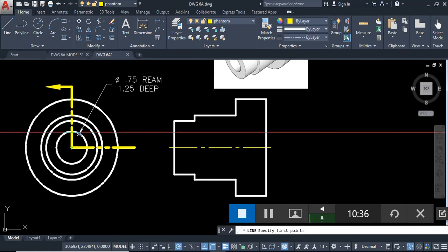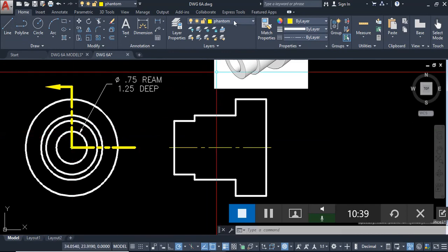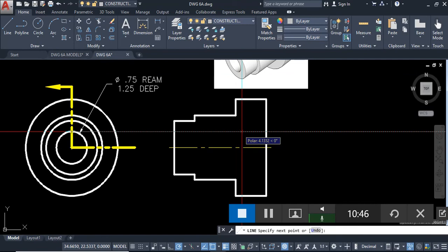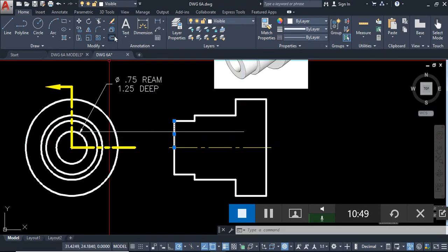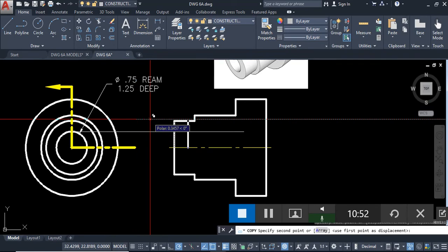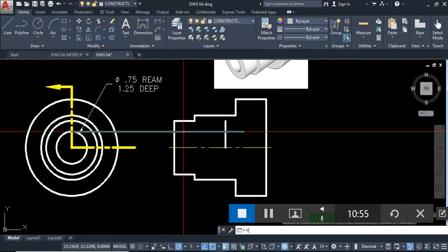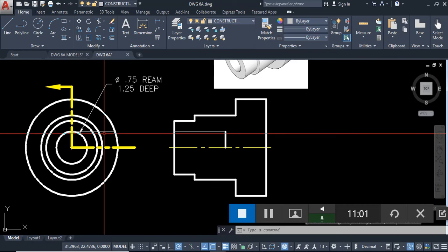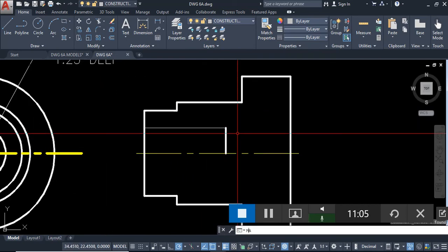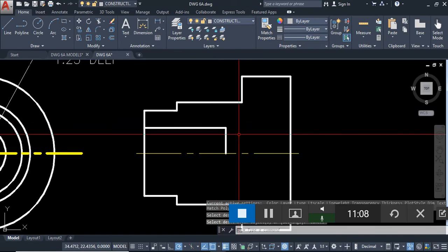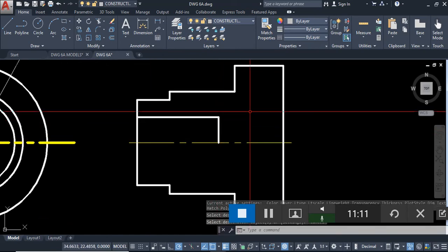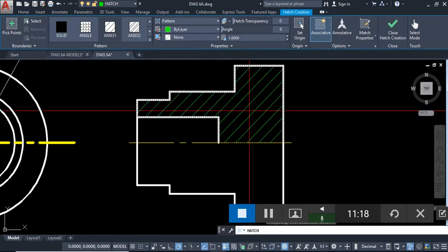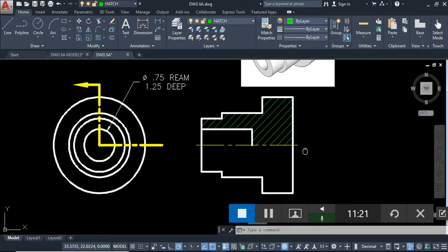Okay, so over here we can project the top of the hole over to the side. We know that the hole goes 1¼ inch deep. Okay, and that defines the hole. Now the rest of this is solid, so the rest of that will get cross-hatching. Right, section lines.